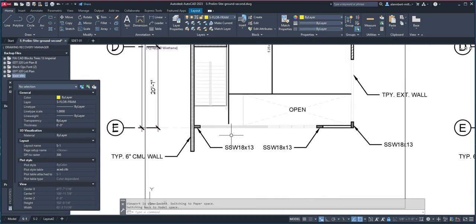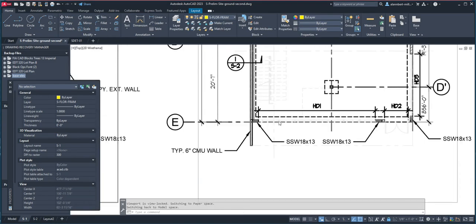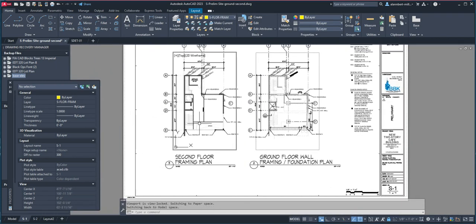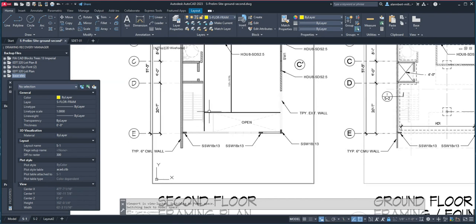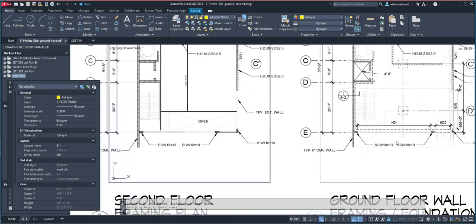Now, we have an opening here, and so that means, if there's an opening on the elevation, that this should really have a column over here. And that's something that the engineer would have to tell the architect: if you want windows all the way here, like this opening, I need a column over here or a column on this side.